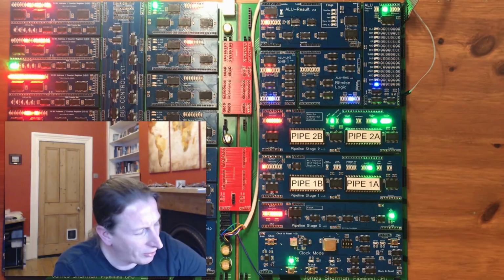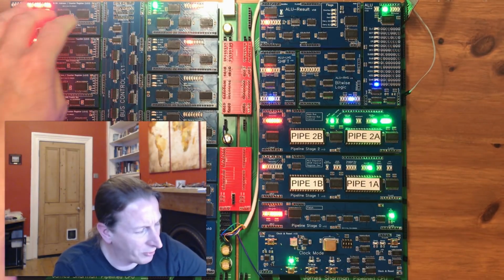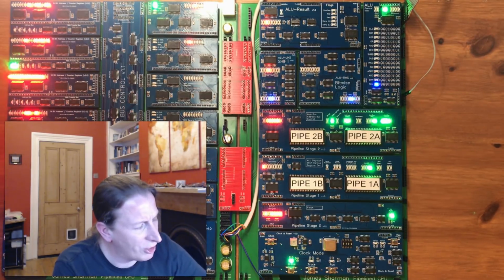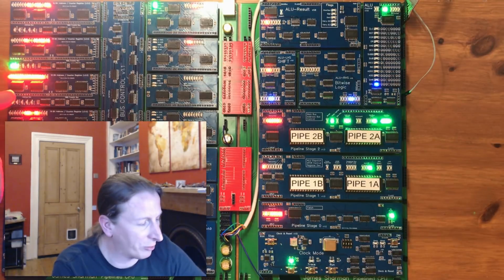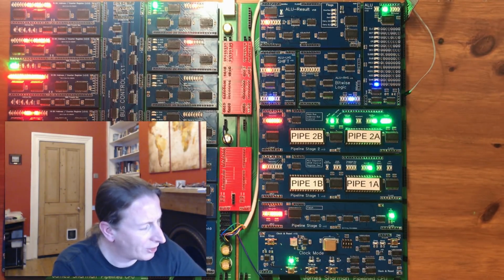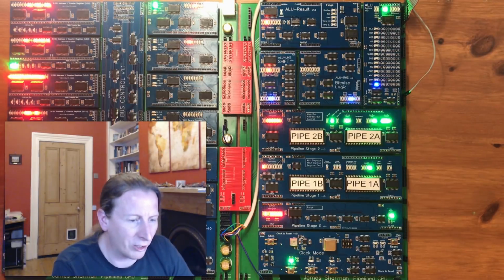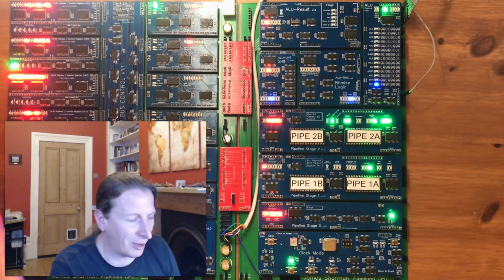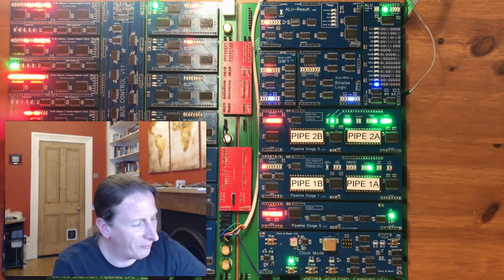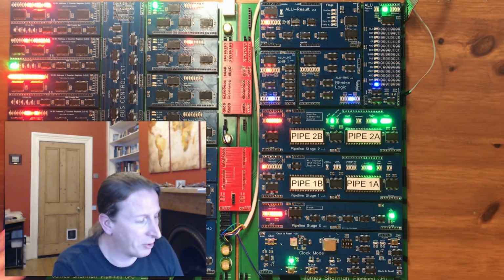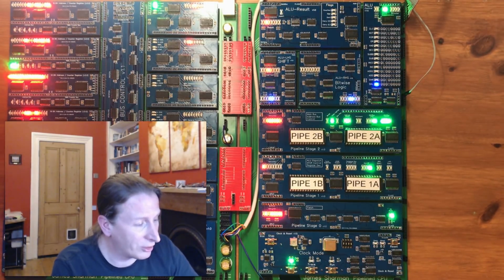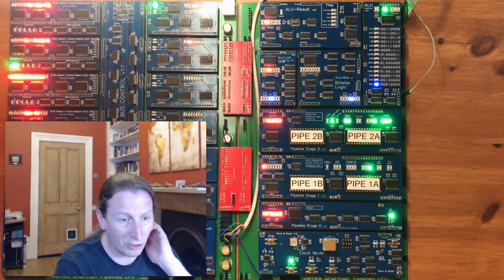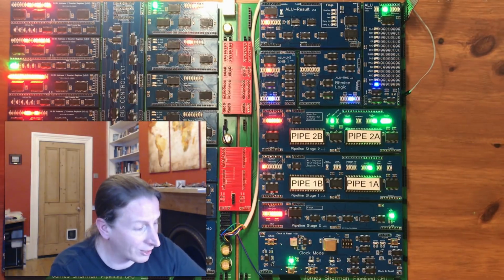The return address and program counter really need the simultaneous update provided by the output latches. The stack pointer is the only thing that really needs the increment and decrement. SI and DI, I have wired in the decrement, but I've not used it very much in code, and if I didn't have it, I probably wouldn't miss it that much. And so there is basically functionality in these registers that I'm not using. I've got the decrements wired up for program counter return address, but I've never used it. I don't think I've currently got instructions in the ISA for even accessing them.